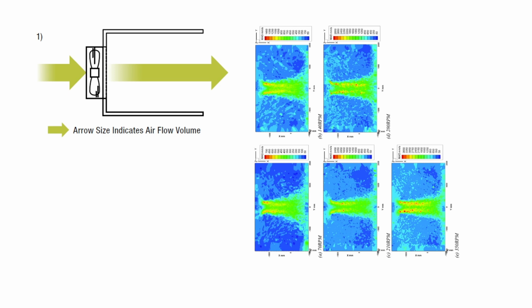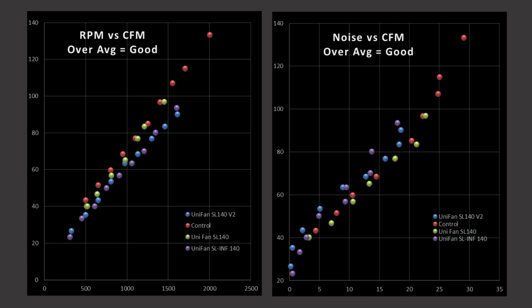The only exception would actually be hwcooling.net, which I really like their cone-shaped testing, and I would like to implement that in the future. Of course, I need to acquire a cone-shaped CFM testing apparatus. And I would want it sized to fit a 180 millimeter class fan so that there's plenty of room for those larger fans to expand air if they have a tendency to do that.